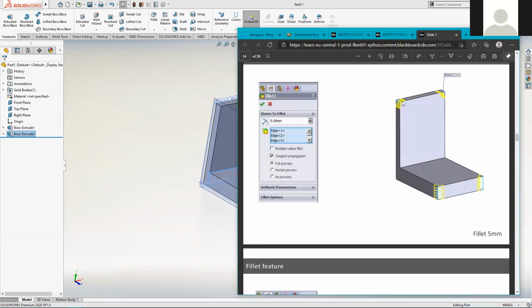That essentially, as I said earlier, takes two faces that meet each other at an edge, and it smooths the transition from one face to the other. The way that it normally smooths them is that it just adds in a little arc, so it adds in a part of a cylinder, I suppose. And you can set the radius of that arc. So when we come to set this up, there's the radius value, 5mm. If this is a portion of a cylinder that it's adding, it's a 5mm radius cylinder. So we'll do that now.